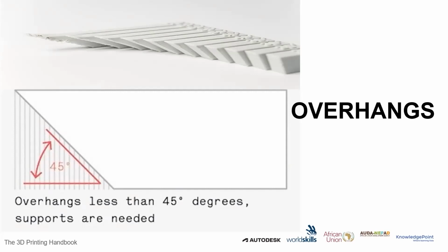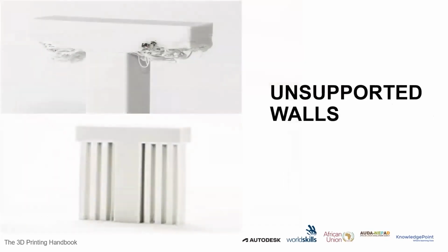You also have to do a little bit more in post-processing, removing the support and also going further with sanding, using finer grades to get the final surface to really get something better, because those points where the supports are will be rougher than the other areas where there are no support materials on the surface. So it's very, very important. That rough surface is something to keep in mind in the procedure.